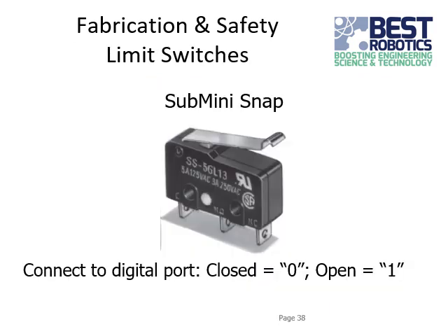Here's another nifty little component called a limit switch. These are just little switches that you can have your code read as a 1 or 0 depending on whether it's pushed or not pushed. This can be a way to have software controlled limits on how far an arm can rotate, or to tell if your robot has bumped up into something that you might not be able to see from the spotter's box or the driver's box.